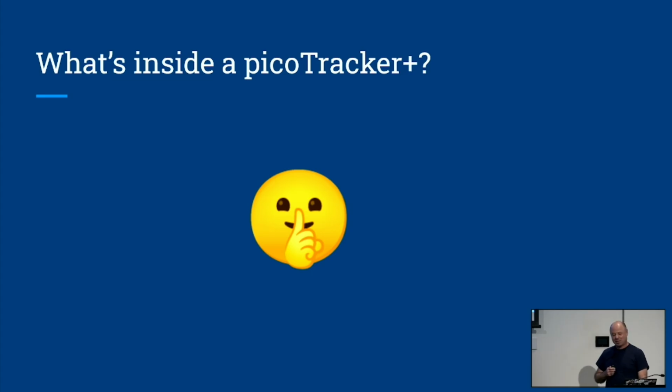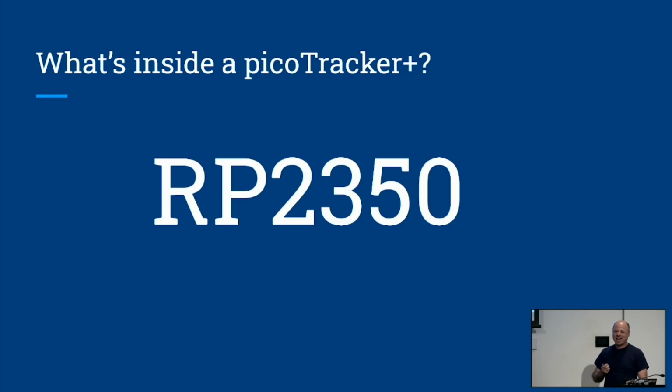So what's inside the Plus? Well, I think I've given the game away a few slides ago. It's going to be based on the RP2350, which is the new version, not the replacement, but the improved version of the 2040 from Raspberry Pi. It's basically double the speed, still dual core, double the RAM. It now has a floating point unit.